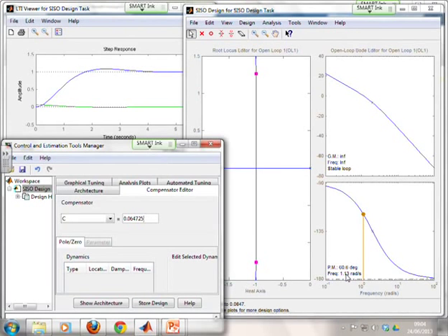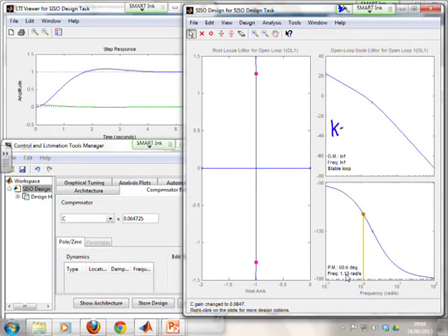So perhaps if I write again, just so that we don't lose it, the compensator that we want, so we want K equals 0.065 S plus 0.11 over S plus 0.2. Okay, in fact perhaps for simplicity I'll just put S plus 0.1 over S plus 0.02, isn't it? Get it right.